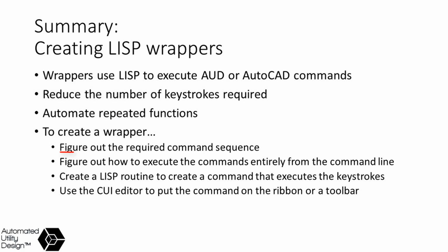To create a wrapper, you first figure out the required command sequence, and what's essential is to figure out how to execute the commands entirely from the command line. Remember that your Lisp command doesn't include any mouse clicks. Once you know the keystroke sequence, you can create a Lisp routine to define a new AutoCAD command that executes the required keystrokes. And finally, use the AutoCAD CUI editor to put the command on an appropriate ribbon or on a toolbar.